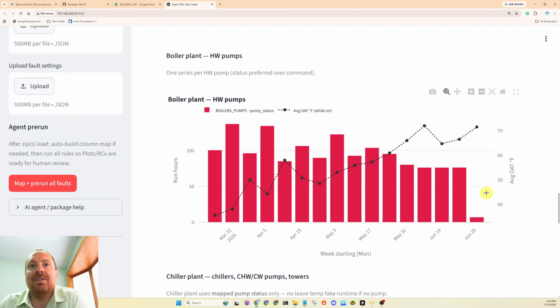So typically what you would see is the building doesn't need heat anymore. The boiler system should shut off, and then there should be some time range during this economizing free cooling window right here that no heat is needed in the building and no reheat energy is needed in the building either for dehumidification purposes. So we only need heat below 50 and then perhaps above 80. So there should be some time range in there where in theory you could shut the boilers off because we don't need to reheat for dehumidification purposes. And we don't need heat.